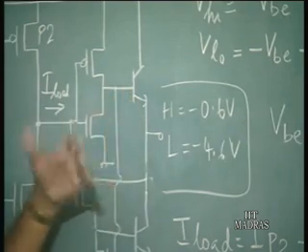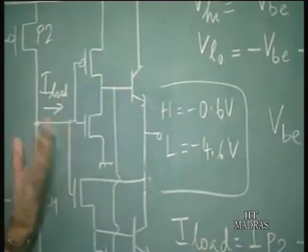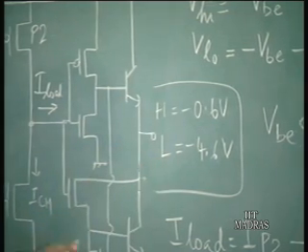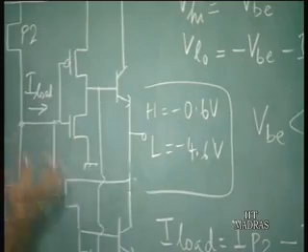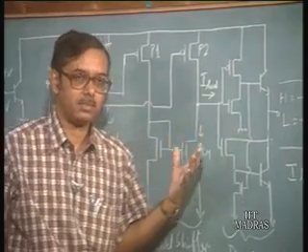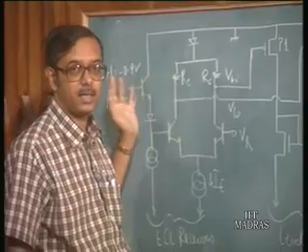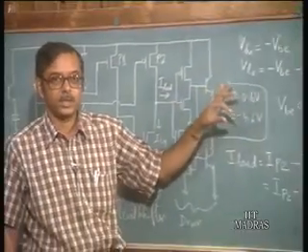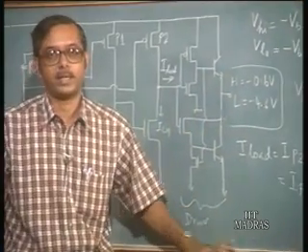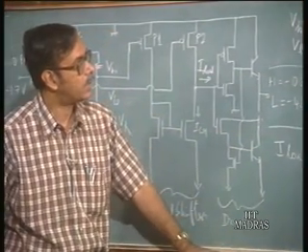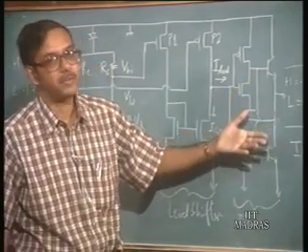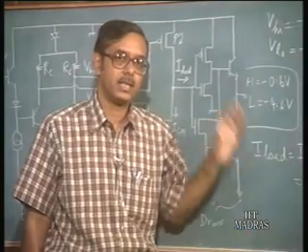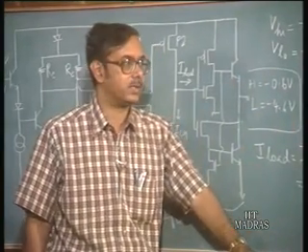Now, once this is done, you can use normal BiCMOS circuits to do the decoding operation. So, this is one way in the BiCMOS static RAM which uses ECL levels: you first convert it to BiCMOS levels, and then follow it up with BiCMOS circuitry to do all the logic operations needed for decoding, as well as for driving the word line capacitances. We use BiCMOS drivers.